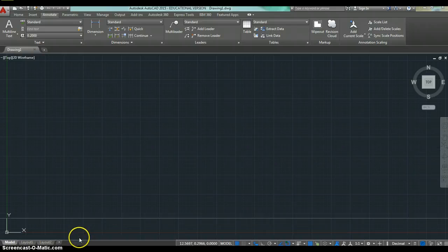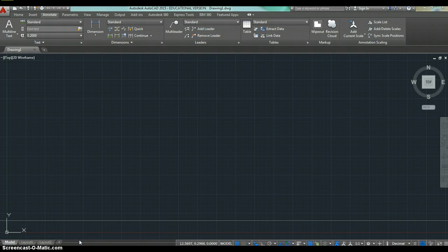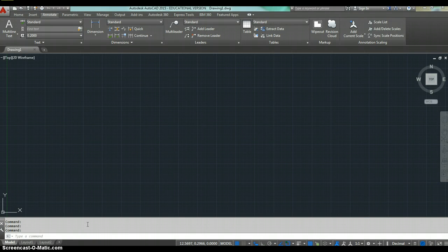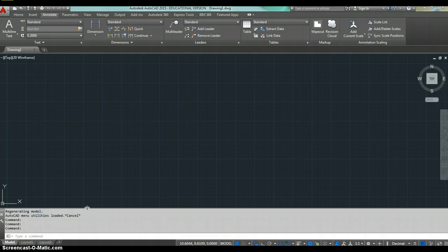And I just want you to come down here to the bottom of AutoCAD and get into that dark black area of the actual software, and you'll get a little outline there. And I want you to release the toolbar at this point, and it will dock the toolbar in there so it's always there, it's always part of your screen, and it'll help us as we're working through this software and as we're learning the software.